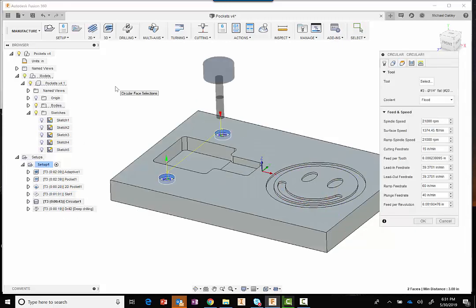And we have circular. So you'll probably use this to cut your wasteboard. Here we have a larger diameter than the tool, and this will just kind of go in here. Again, I've slowed this feed rate down quite a bit. If you're going to be cutting 60 holes or more, you could certainly speed that up, especially with MDF.